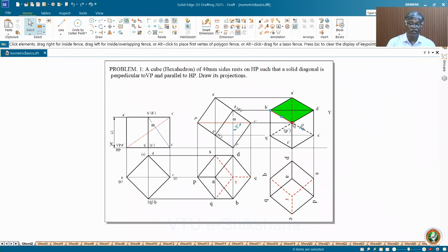See, this axis here, CB, CD, CR, all are equally inclined to each other, 120 degrees each to the other. So that's why it is the same, that is iso. That's why it is called isometric projection. Other projections are trimetric. In general, it is called axonometric.